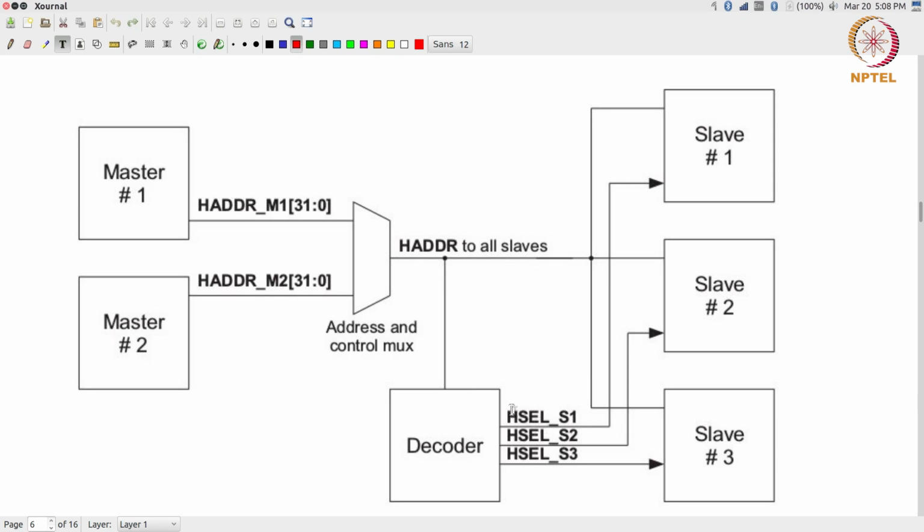Okay. So, we already saw that is how memory mapped interfaces work. They take out part of that 32-bit address, maybe the top 16 bits, decide that if it matches something like 4120 etc., it corresponds to the GPIO peripheral. If it is some other number, then it corresponds to the FFT peripheral, right, and therefore generates a select signal corresponding to that.